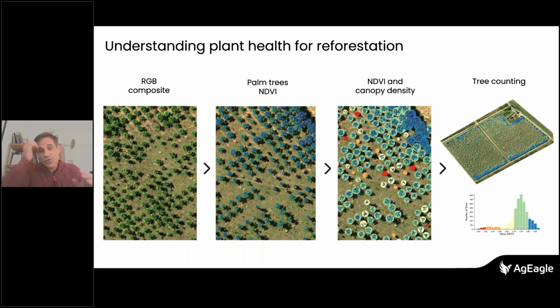The trigger options are the following. You can have an external trigger. You can trigger by overlap, so it works independent of the speed and the altitude where you're flying. Say, okay, I want to have 70% overlap, always starting from a certain altitude. On YouTube, we have a link that explains how the configuration of our camera works. You get into the camera, right? And you can simulate the map you're going to fly. After you're done flying, you can simulate the overlap, so you can see if there are any gaps or images that have not been taken, or if the flight plan wasn't good enough.